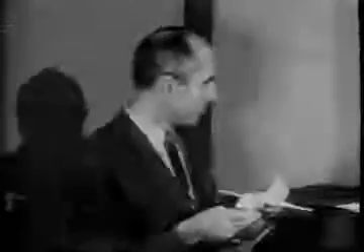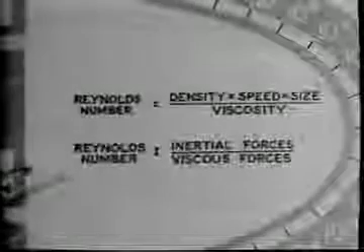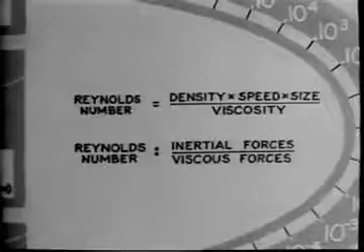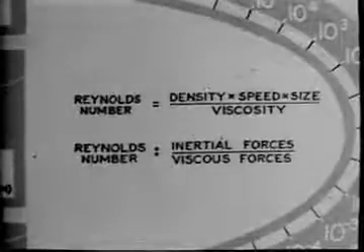The Reynolds number shows us something else, for it is a measure of the ratio of the inertial forces to the viscous forces in the force balance. A very, very low Reynolds number, for example, means that the viscous forces are so large compared with the inertial forces that the inertial forces may be neglected.